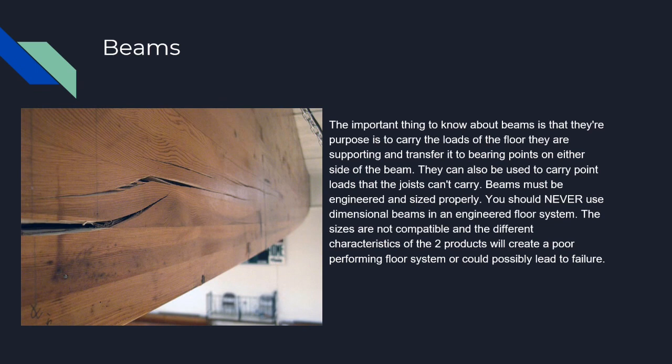The important thing to know about beams is that their purpose is to carry the loads of the floor they are supporting and transfer it to bearing points on either side of the beam. They can also be used to carry point loads that the joists can't carry. Beams must be engineered and sized properly. You should never use dimensional beams in an engineered floor system. The sizes are not compatible, and the different characteristics of the two products will create a poor performing floor system or could possibly lead to failure.